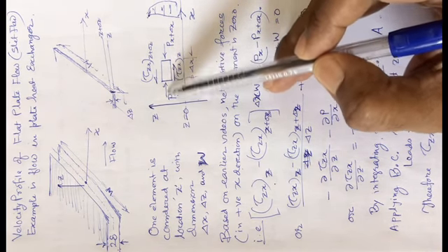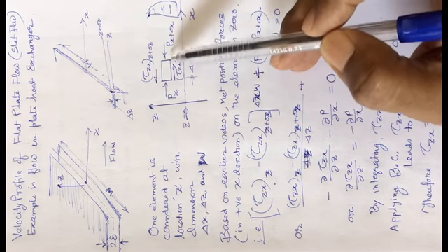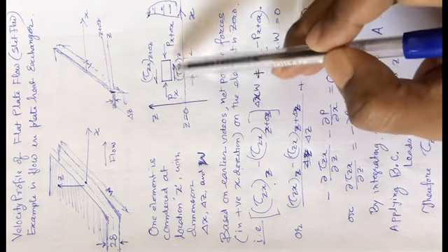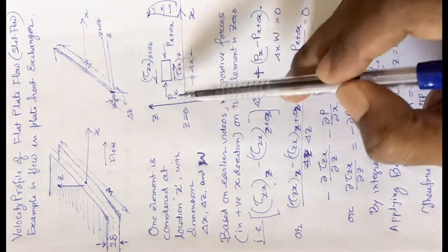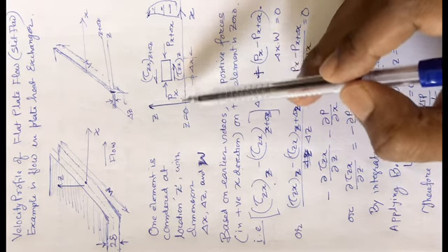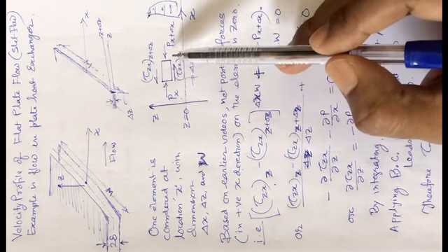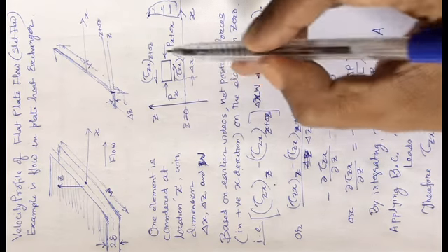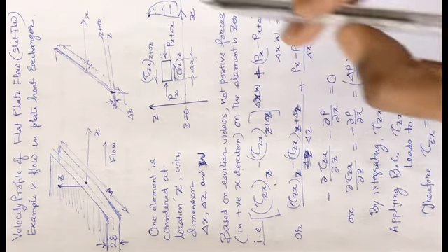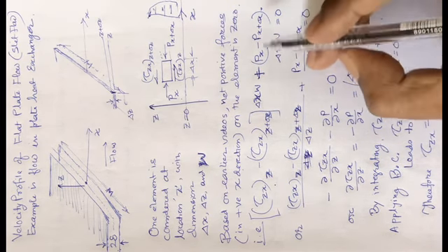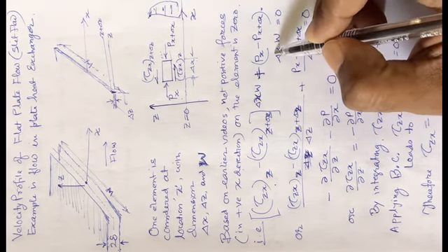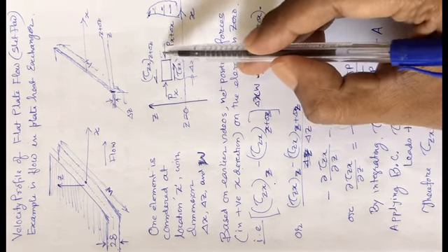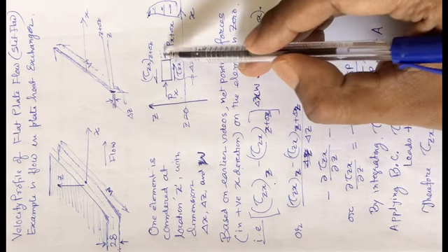What causes the fluid to flow is the pressure. From the left hand side there is P at x, and from the right hand side P at position x plus delta x. Now P at x is supposed to be greater, and only then will the fluid move from left to right. So the positive force is P at x minus P at x plus delta x, multiplied by this particular distance, delta z into W. This pressure force is acting on this height, delta z, and depth W across this plane.